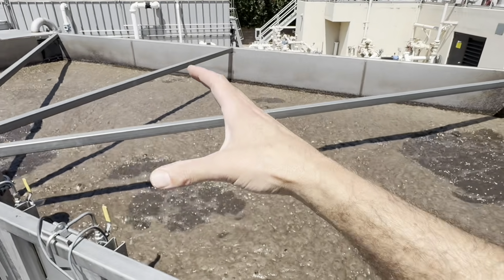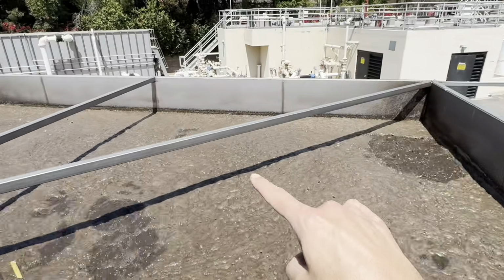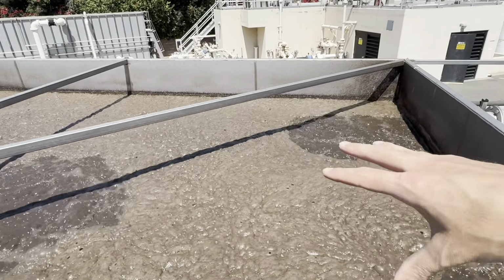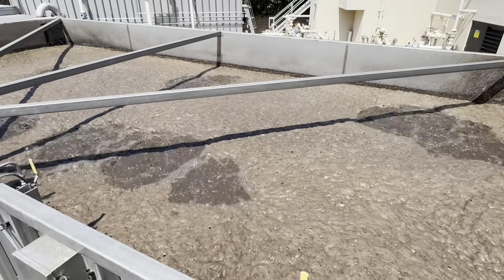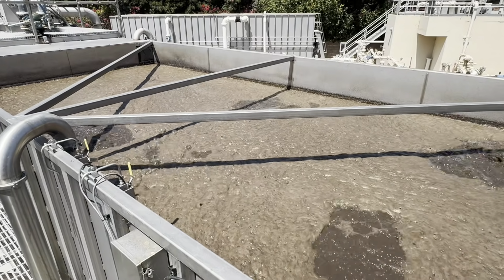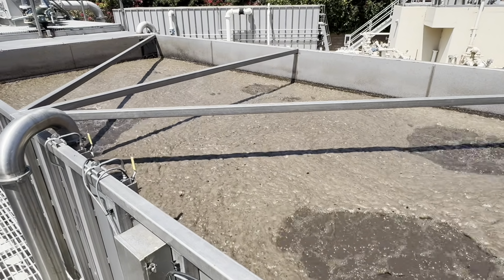This is a plug flow, meaning it starts there and ends here, and it just kind of moves linearly. And then by the time we get here, and I'll talk about this on the whiteboard, the BOD is pretty much gone, and then it moves to the next process, which you're gonna hit in a second, and that's where we're gonna manage the TSS. So this is the mixed liquor suspended solids, which a high percentage of it is the volatile suspended solids, and that's kind of how an aeration basin works.